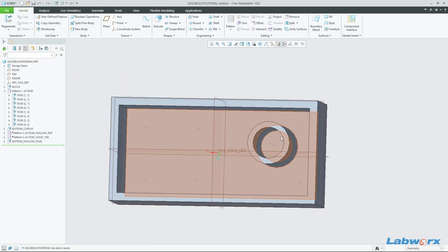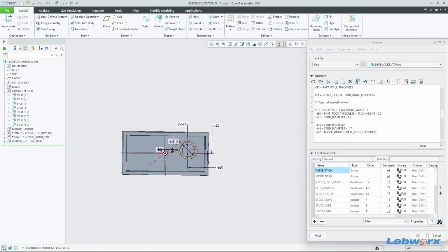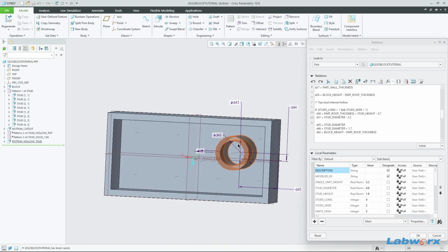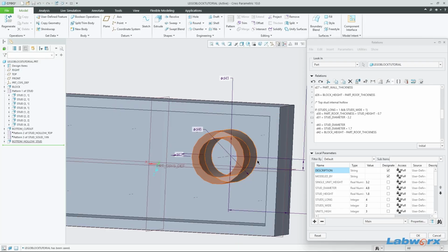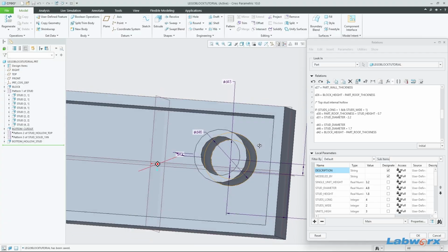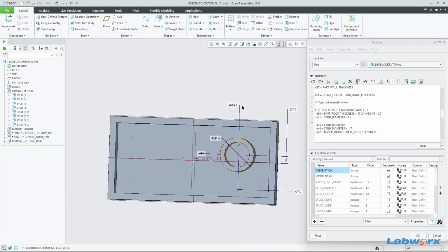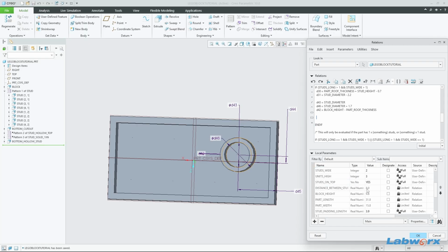Because we know that that's going to be the first stud, the first hollow stud, we are going to set the dimensions to locate that first stud. And then from there we'll pattern out. So we know that to get into the center of these first two studs, we need to go in 7.9 millimeters from each of the sides, which is our spacing between studs minus 0.1.